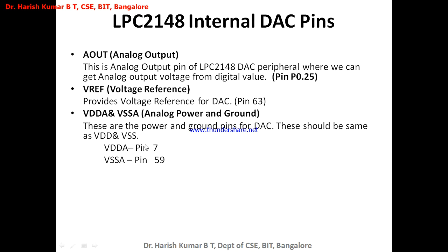Now what is the pin? Pin 7 is VDDA and pin 59 is VSSA, and again these two pins are connected to the DAC which is there inside the LPC2148. I'll show you here.